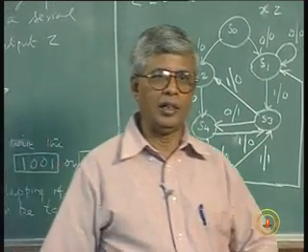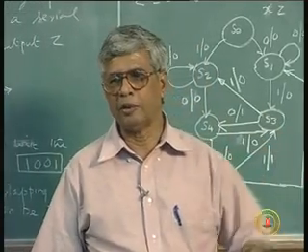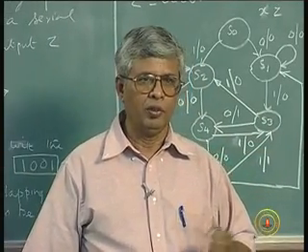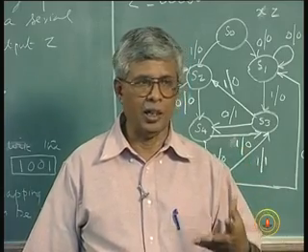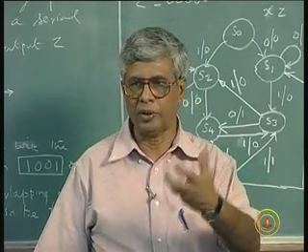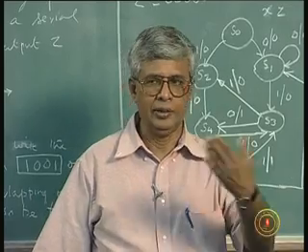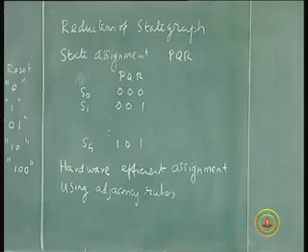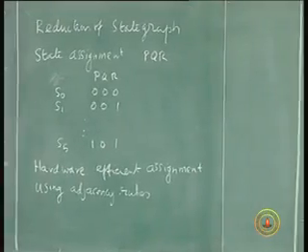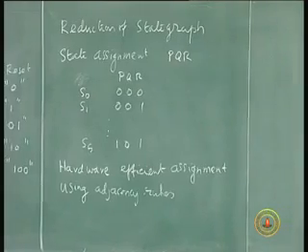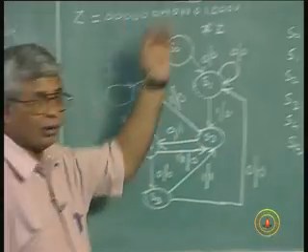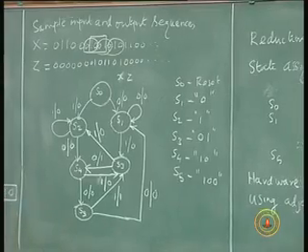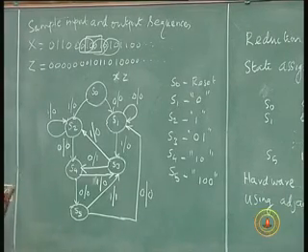If the flip flops are other than a D type, you draw a transition table which is other than the state table. From there you draw the Karnaugh maps and simplify and then draw the gates, the steering logic using gates and the flip flops which will be driven by this steering logic, and then your circuit is over. Then you start giving the patterns, build it and test whether it works, because this is only a sample sequence. You do not have to give the sample sequence, you should be able to give any sequence. Whenever you give any sequence, this pattern is identified, it should immediately give an output of 1.